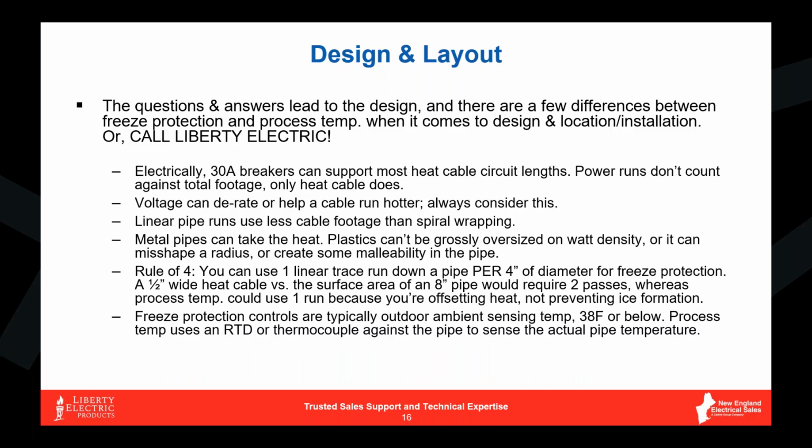You're really just totaling up what's your actual footage of heat cable on the circuit, not of supply power. Voltage we're going to touch on in a future slide here, but voltage plays a big role in your heat output on that cable.